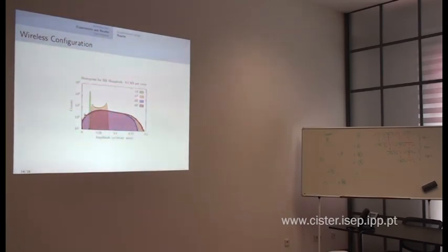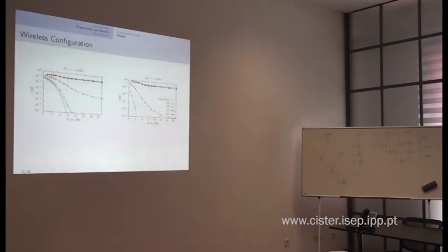But as you start to add more repeaters, it just happens. For example, here you see the 2 amplitudes are not the same. Otherwise, this spike here would be 0. So they don't go completely depressed, but the observation says that it gets somewhat depressed. And when we add noise relative to the peak of the signal, this area here will be vulnerable, and that's why we get some errors here. But you see, it's still reasonable.